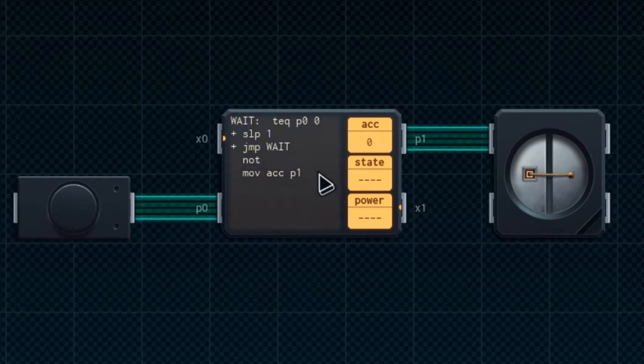So we need to sleep here somewhere. One of the solutions that we can do to this is to add a simple cooldown. Let's add a cooldown of 4 in here. So whenever we press the button, we do the inversion and the output, but we wait 4 time units before we do anything else.